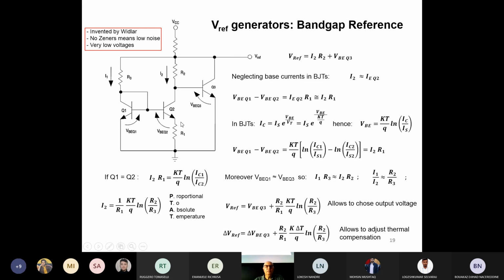This voltage drop has as a result that the two base-emitter voltages of the two transistors are different. In a simpler current mirror, the two transistors have the same VBE. Here they have a slight difference. Usually the VBE of Q2 is smaller than the VBE of Q1.